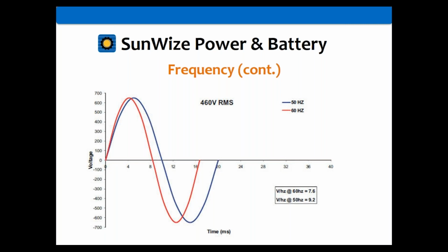Well, when you actually talk about AC, you're not talking about the peak of the waveform. We're talking about something called root mean square, which is different. So when you start talking about 120, 240, you'll notice that your actual peak waves are higher than that. So it's just something to think about and consider. Again, we'll get into more detail when we start talking about root mean square in a different webinar. Don't want to go into that too much detail here, so we'll table that for another conversation.